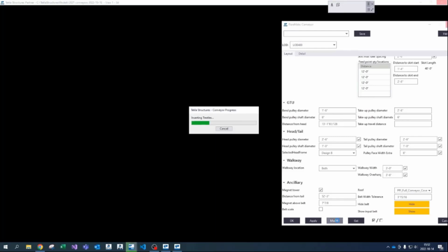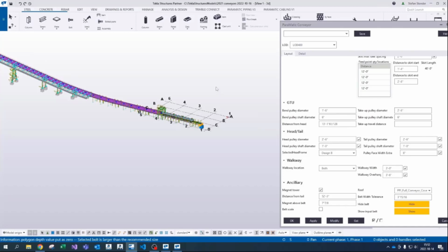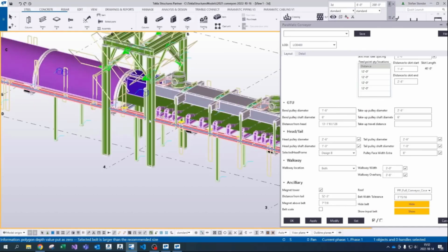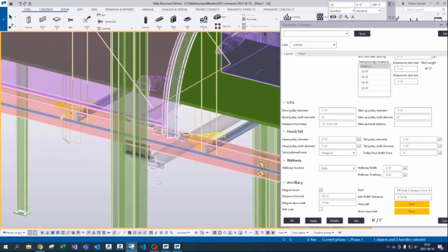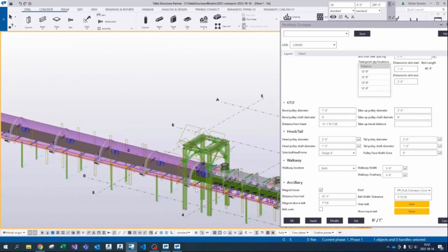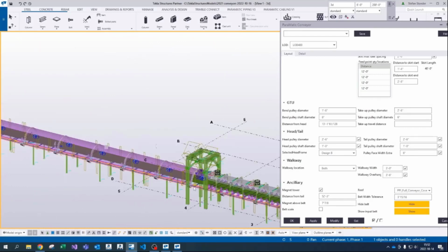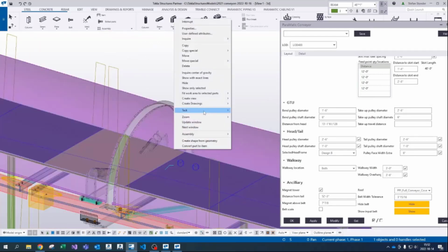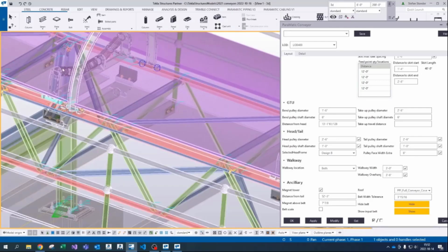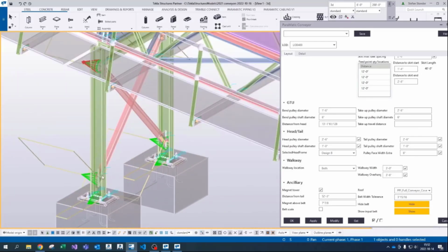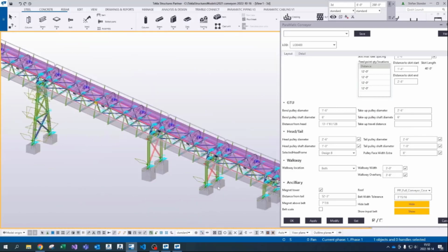From there we go over to level of detail 400, where we include all of the detailed connections, as well as idlers. It includes even the packers. So for those of you who understand conveyors, when you have a curved conveyor, concave conveyor, you have to pack the idlers because you have straight sections. This application automatically calculates the quantity of packers required.